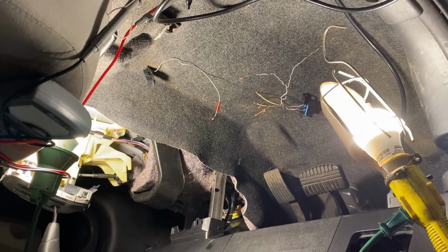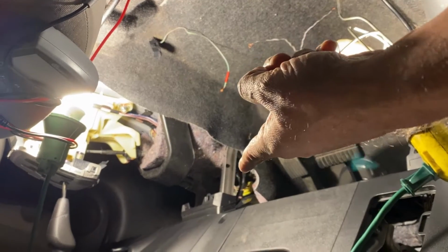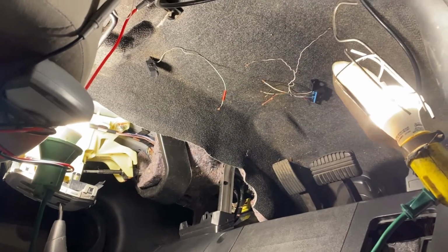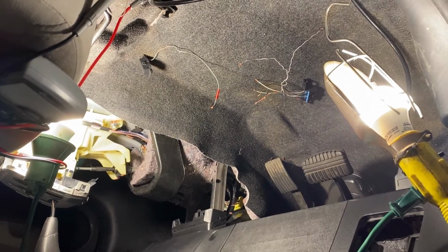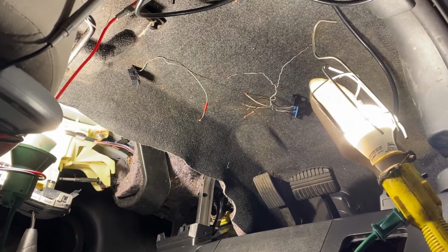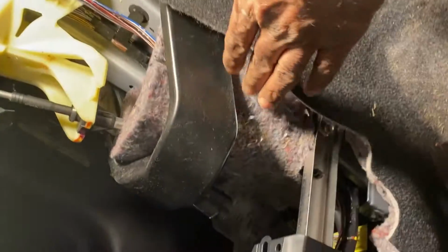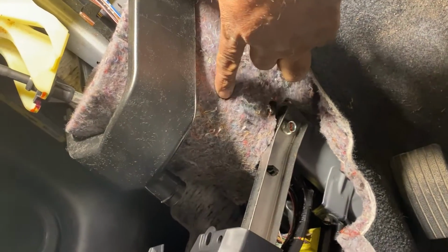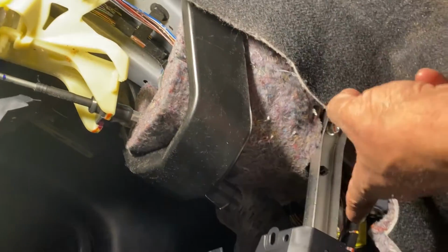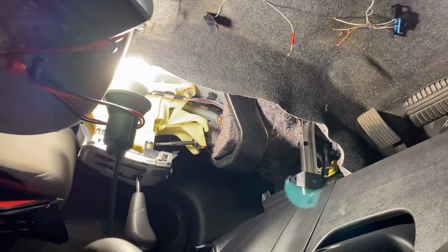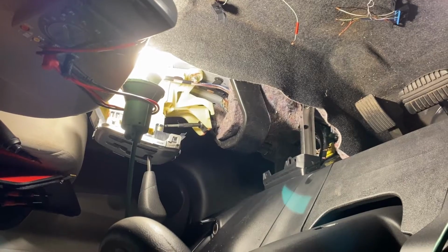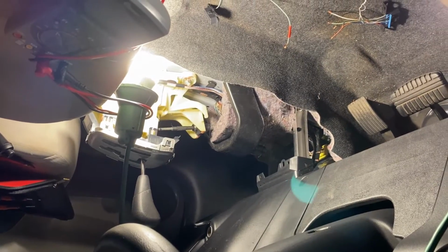again. But at least I know that I have power, and my CAN bus is good, even when I run a power test. Since I see this, it looks like a mouse was here because the car was sitting. So I measured the power to the airbag all the way to the front, and I have no voltage drop. But because I do it with two hands, I couldn't get it in the video.